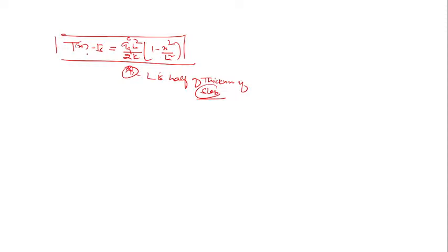And where is the maximum temperature? At which point is there a maximum? You can see this equation will be maximum only when x equal to 0. So T becomes T max at x equal to 0, meaning at the center of the plane. So T max minus Ts, the difference between the maximum temperature and surface temperature, is equal to qg dot into L square by 2k.